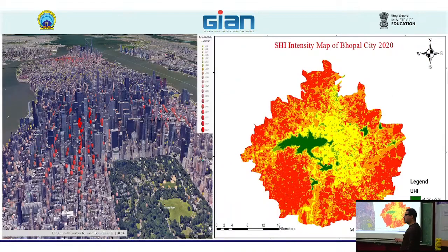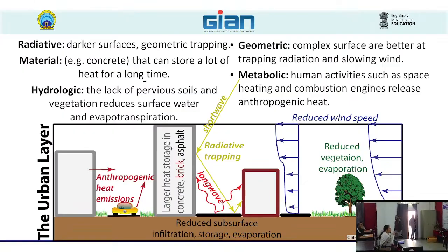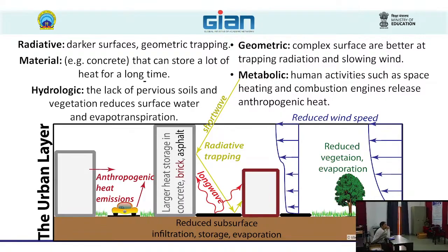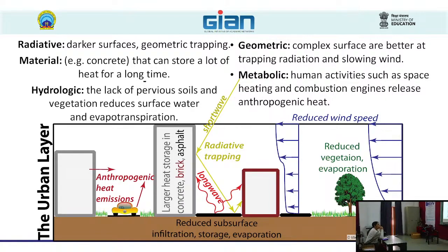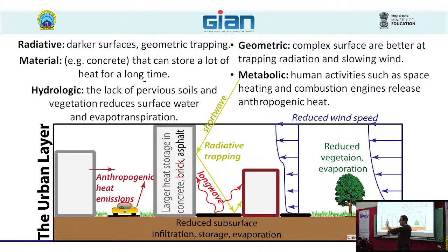I have one question. Yes? The short wave has high intensity, but the long wave has very low intensity, right? Yes, yes. But it is important, it is very important. You also need to put a pyranometer to measure how much is outgoing. Outgoing radiation, yes, this is what we measure. So we measure the downward and the upward.